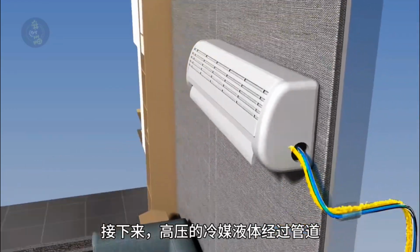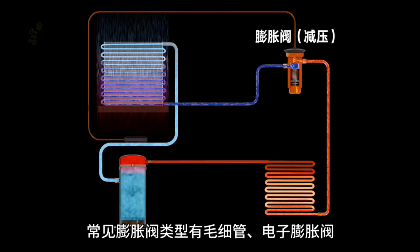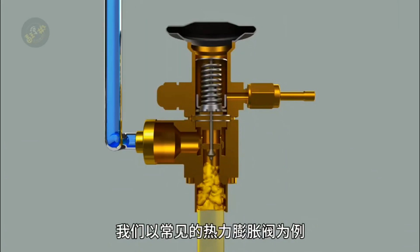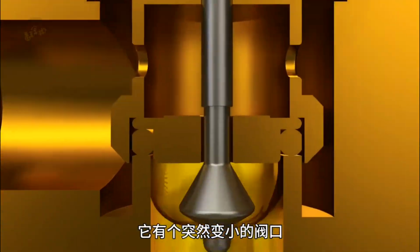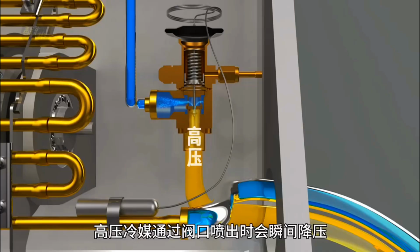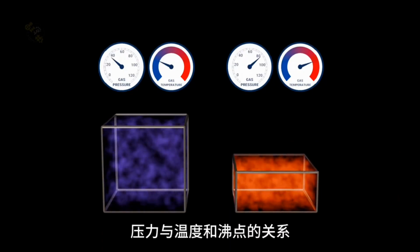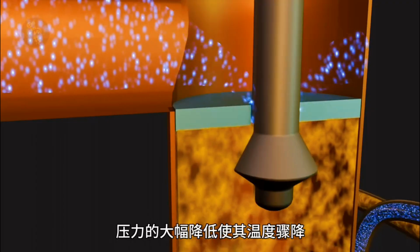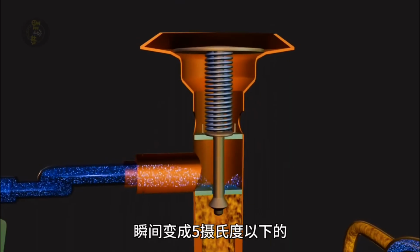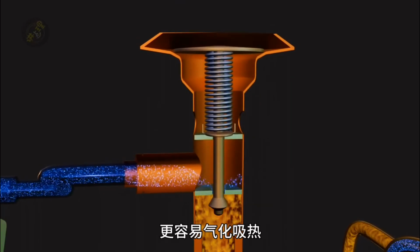Next, the high-pressure refrigerant liquid flows through a place called the expansion valve via a pipeline, which is a pressure-reducing device for the refrigerant. Common types of expansion valves include capillary tubes, electronic expansion valves, and thermal expansion valves. Let's take the common thermal expansion valve as an example. It has a suddenly narrowed valve opening with a needle valve in the middle controlling the flow of the refrigerant spray. As the passage narrows, the flow rate is restricted, and when the high-pressure refrigerant sprays through the valve opening, it instantly depressurizes and partially vaporizes. According to the relationship between pressure, temperature, and boiling point we just mentioned, a significant drop in pressure causes its temperature to plummet, instantly turning the liquid from 30 to 40 degrees Celsius into a low-temperature, low-pressure liquid-gas mixture below 5 degrees Celsius, with a lower boiling point, making it easier to vaporize and absorb heat.